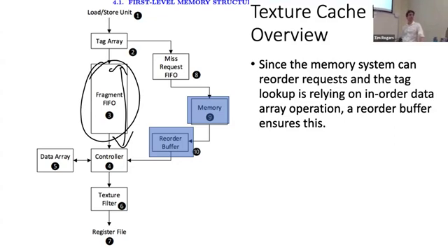Okay, other questions? Even though this seems weird because it's graphics, it is just loads and stores and math, right? Everything that we operate on is just loads and stores and math. After you get out of the texture cache, it's treated sort of like there are some other operations when we start to look at the L2 where we can do operations sort of like a PIM out in the memory space that graphics does. We'll talk about that when we get there. But generally, you're just doing loads and stores to the memory system. Okay, other questions?